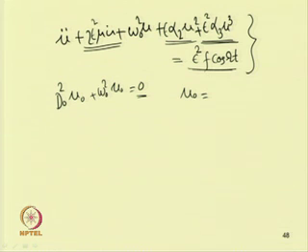But if we make the forcing term of the same order as the linear term, then the right hand side will be f cos omega t. In that case, in addition to the free vibration part, the complementary part, one can add the particular integral. Depending on the actual nonlinearity of the system, one can use different ordering, get a wide range of equations, and by solving those equations get the actual response of the system.